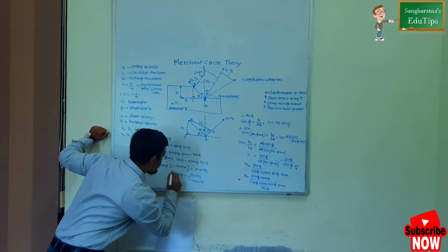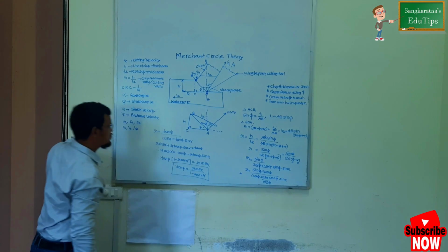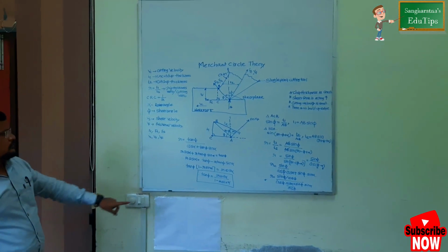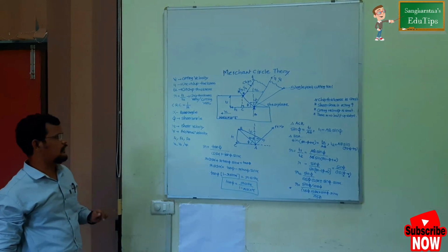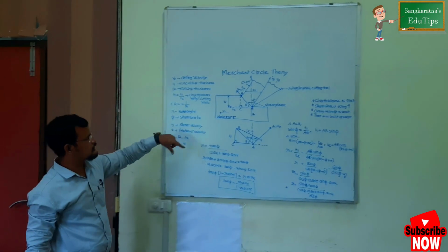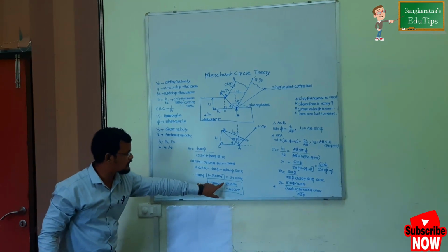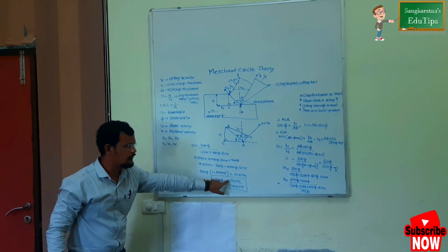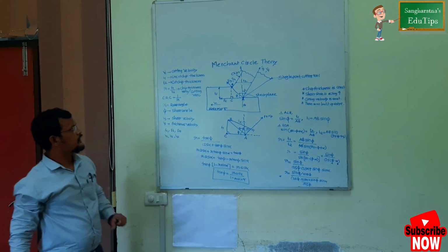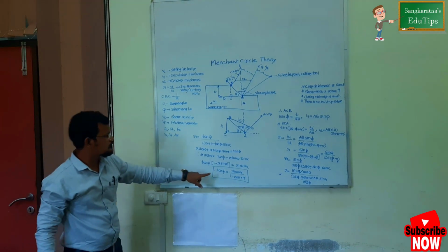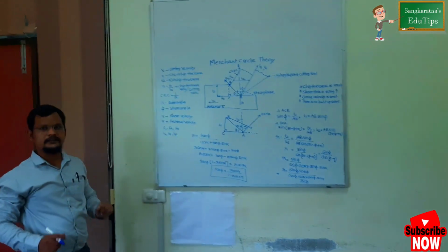So this equation is actually very important from the GATE point of view as well as the examination point of view. This will definitely be asked in the examinations, how to derive the shear angle. With this calculation we can easily determine tan phi. Once we know R, the rake angle will be given, and the chip thickness before cutting and after cutting will be given. So we can easily determine the shear angle phi from this equation. I hope it is clear now.